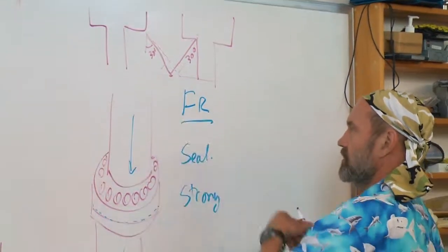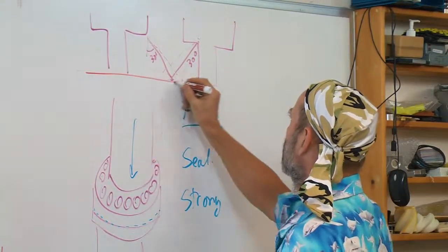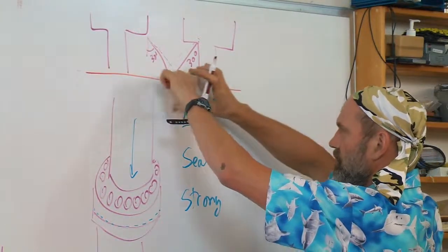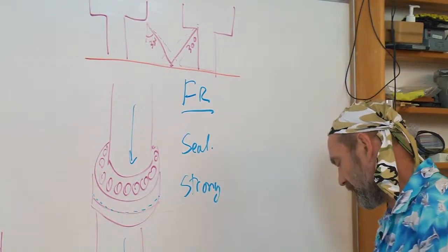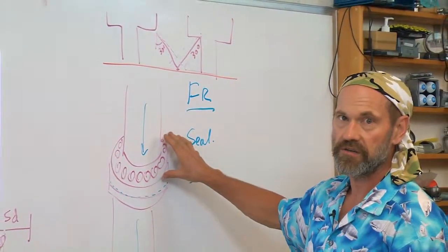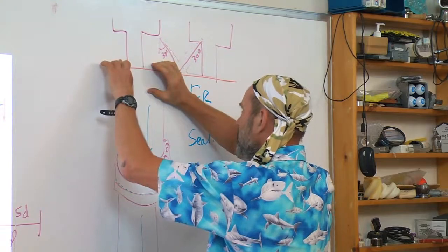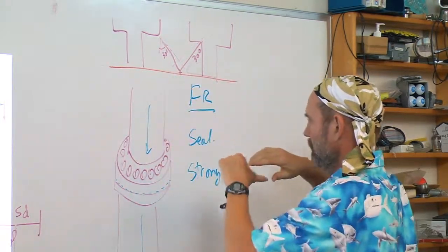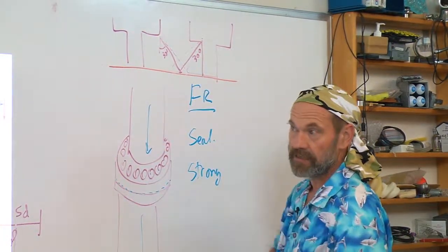What happens then is whatever seal you have in here, like a gasket, is then feeling pressure from the bolts to the joint everywhere. That becomes very, very important. So things don't fall apart. If the gasket is preloaded by the joint pressure, and there's a part of the gasket that doesn't have any joint pressure, the pressure in the pipe then can act to tunnel its way through, and you get a leak.